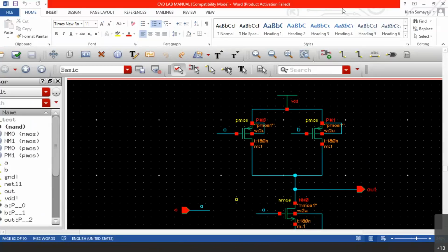Okay. The answer is something strange. I know that you will not be knowing this answer, but at least I want to make you curious about the answer. The answer is something strange. Actually, it should be called as POSFET, not MOSFET. Why? The reason is, it is polysilicon oxide semiconductor. See, at the gate there is polysilicon, then there is oxide, then there is this channel. Channel is semiconductor. So it should be called as POSFET.